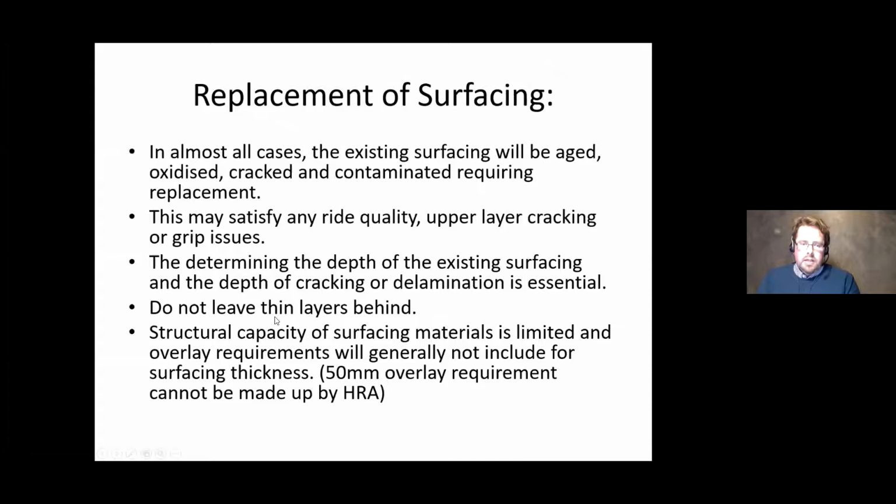And be conscious as well that the structural capacity of surfacing materials is limited. So if you get an overlay requirement, you can't make that up with HRA. If the PMS, the FWD company comes back and says you need a 50 mil overlay, you can't make that up with HRA alone. SMA has some structural capacity, but not enough to do it. So you're really looking at removing your surfacing, overlaying 50 mil, and then replacing with a similar depth of surfacing.